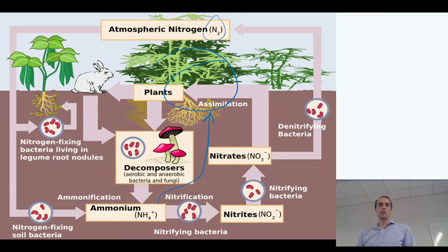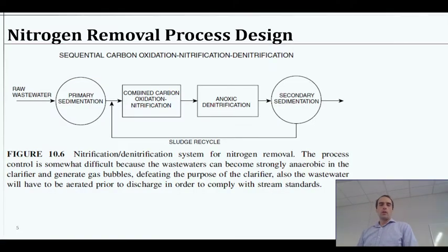Denitrification, going back to, excuse me, nitrogen gas. All right, so nitrogen removal processes, in practice, in a way we often think of them as a tertiary treatment step, because we've got that primary and secondary, and then anything else we add that's going to be fancy is sort of tertiary. But we can also put it directly in line or in step with the secondary treatment process.